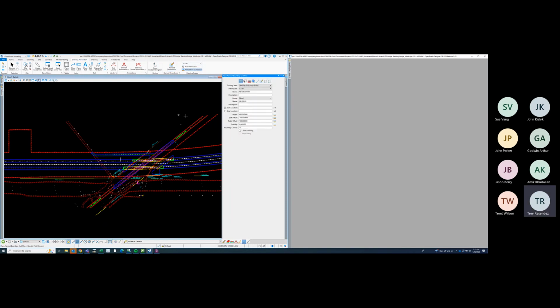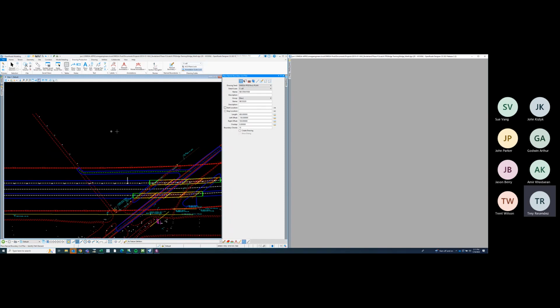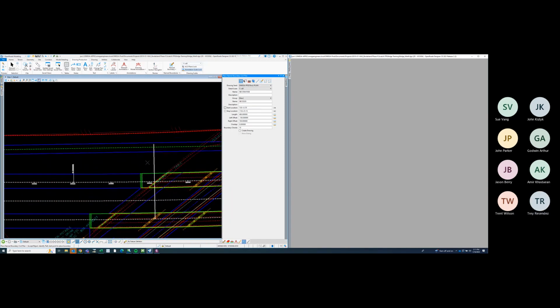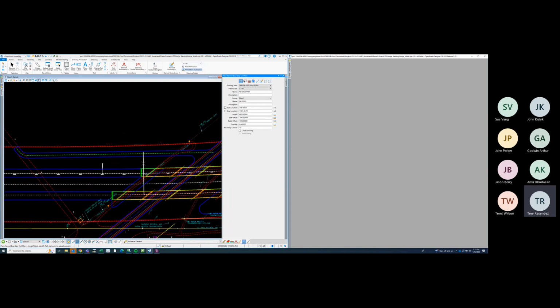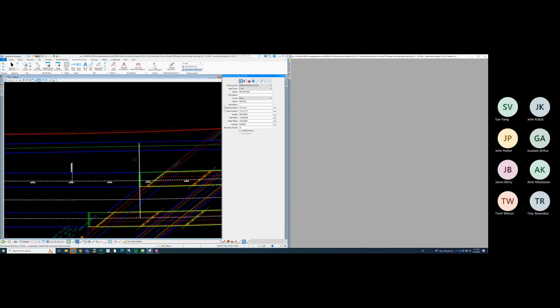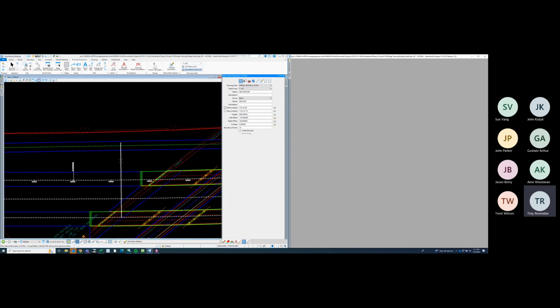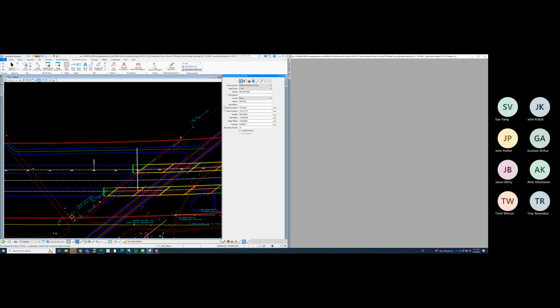See name boundary. Okay. So I'm just going to do the same thing, right? All I did was click name boundary. I'm going to select my alignment, and now I see this white line here. So I know what the start of my sheet needs to be. So I know that it needs to be at, check real quick, it's 7:18:10.